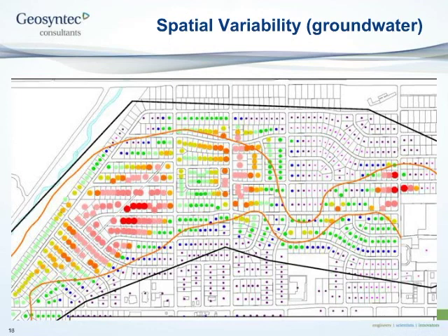This entire lobe of the plume was identified by the fact that some indoor air concentrations that were elevated were detected in these homes, and additional sampling detected in more homes and more homes and more homes. So at this particular site, houses were used almost as flux chambers to map the groundwater plume, which was to everybody's chagrin after they thought that the plume was originally mapped to be just in a short distance. So spatial variability depends on geologic heterogeneity. We as hydrogeologists are used to dealing with geologic heterogeneity, but it does have a big impact on vapor intrusion assessment as well.